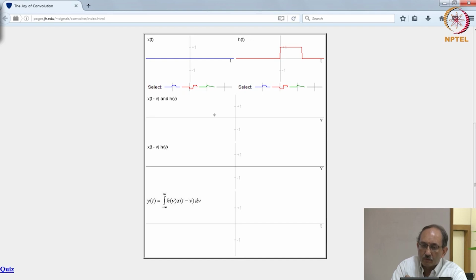Now let us clear the first curve. Now, I will again convolve two square pulses, except now the first square pulse is going to be this. It is roughly the same width as the first one, and now let us look at where the T point is. Now, you can expect the pulse which is now to the left of the origin, after flipping it will be to the right. Therefore, the reference point which was at the leading edge before now will be at the trailing edge. So, that you can see here.